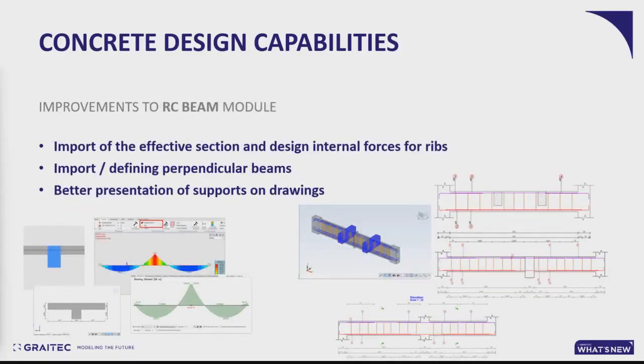Now, 3 quick points related to improvements to RCB module. First, with new version, when a rigid beam is exported from advanced design to RCB module, instead of a rectangular beam section, the equivalent T section is imported with integrated design forces also.